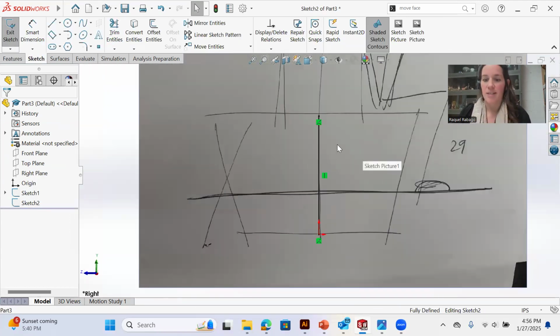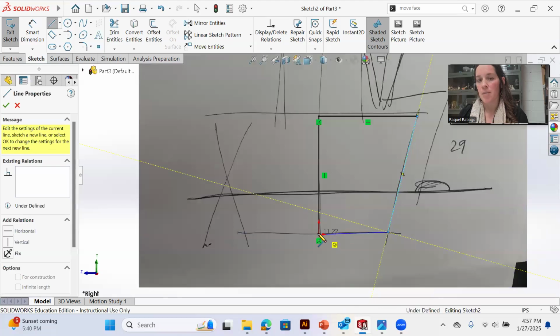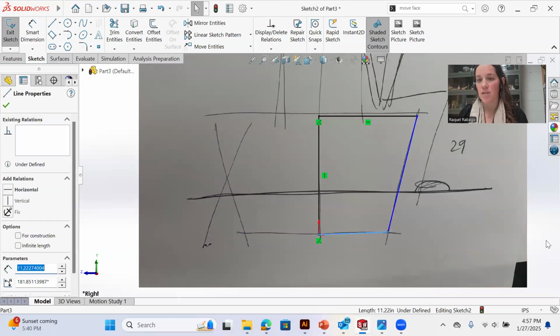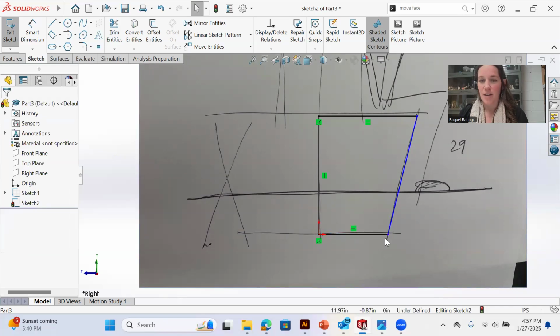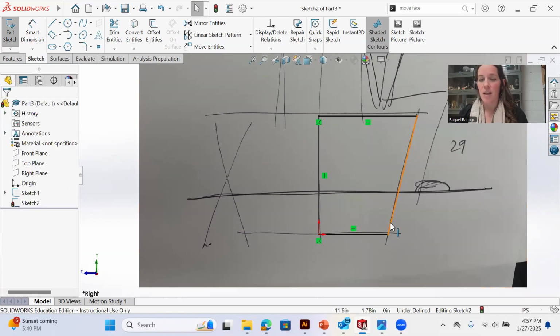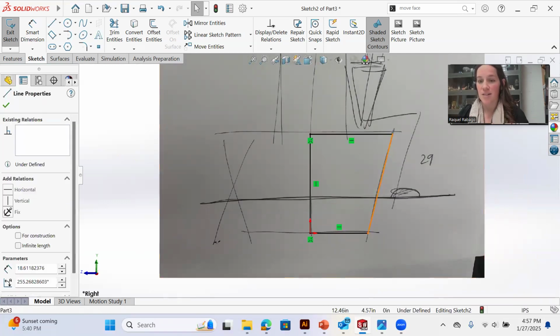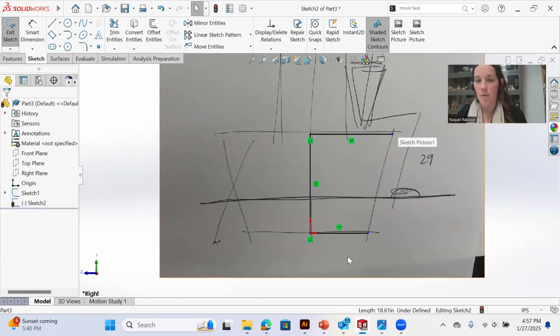Okay, back in. So I'm just going to draw a simple shape. And this is seeming maybe a little too simple because I don't just want it to be like a wedge. But I do know the ground plane needs to be flat, sit on the ground plane. So I will click on that line, and then over in this panel, or by right-clicking on it, you can make horizontal or make vertical. So those are two super easy ways just to give it a little bit of definition so that when you do the next thing with it, it's not buckled up or down. So we want that to be nice and flat.